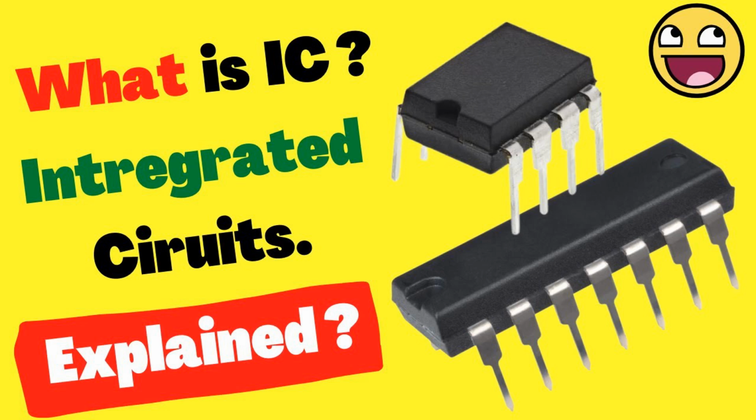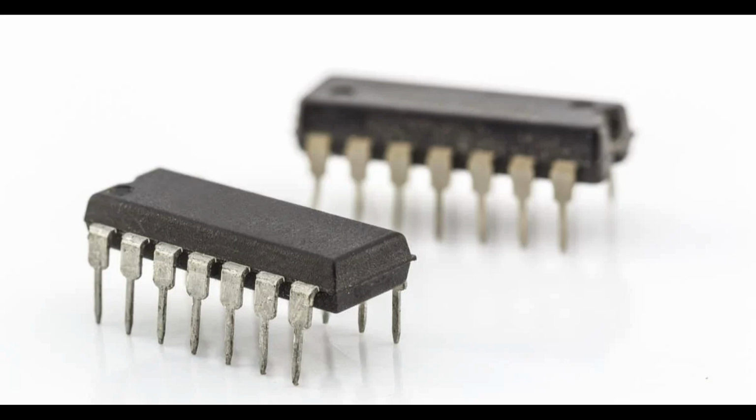ECL, emitter-coupled logic. Uses bipolar transistors in a differential amplifier configuration. Known for high-speed operation and low propagation delay. Consumes significant power, primarily used in high-speed applications like telecommunications and signal processing.